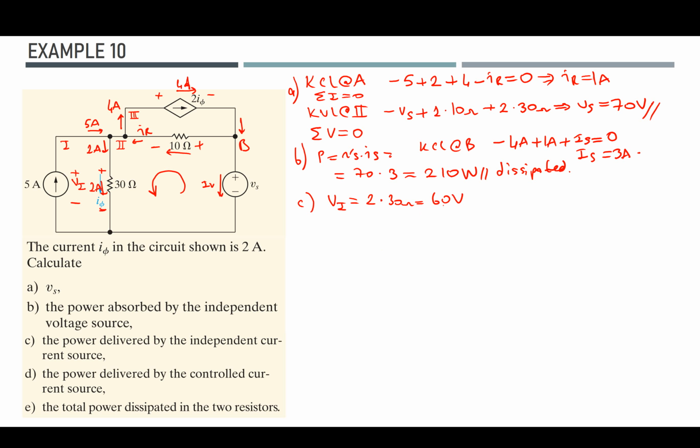So we have the 60 volts, but the current direction and the voltage direction are opposing each other. That's why this is a generating source, and the total power generated by this is V times I, which is 60 times minus 5 amps. Here the minus 5 comes from the fact that the arrow points upward, which opposes the voltage direction. Because of that I have to put that minus sign, so we have minus 300 watts generated.